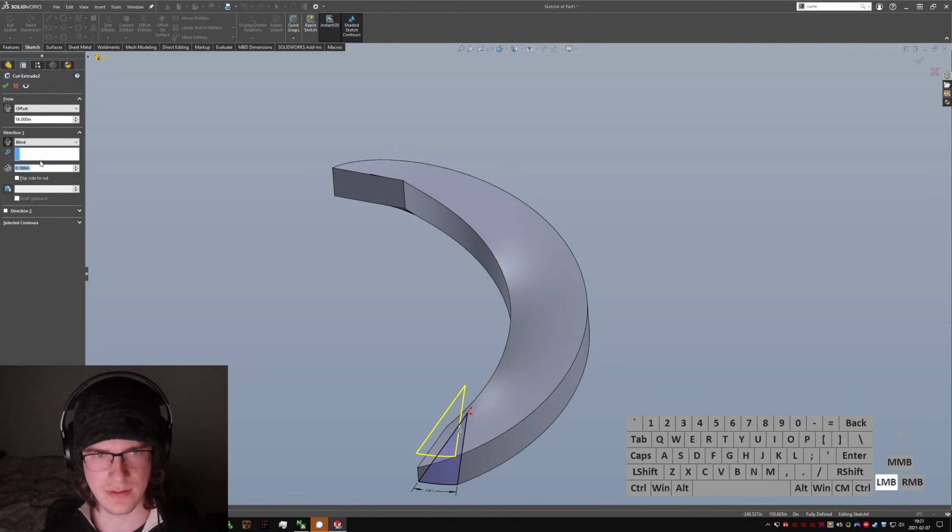I don't really know what's causing these sliver faces. I'm sure if you look at these arcs... Nope, it says those are... Oh, goodness. Hang on. Draft analysis. It's time for draft analysis. Oh. No. Oh, there we go. Yep, they are slightly... They all say they're at 90. It's very rude of them. And it's giving me arc lengths for all these faces, or for all these outer edges.